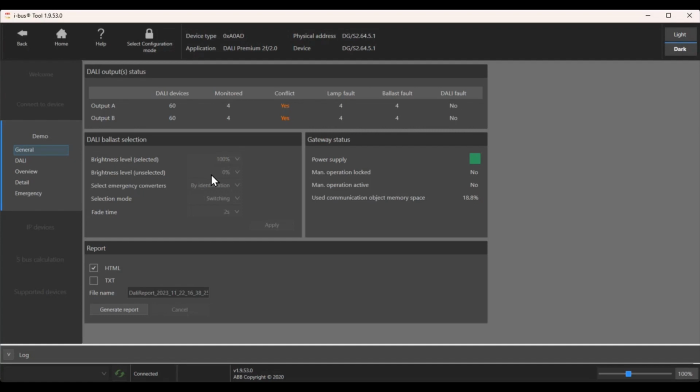As long as they're connected to power inside the site and they've got Dali fittings on them, without any programming, without any integration, without any KNX bus, these can be turned on, and the installers, being the electricians, can press a broadcast button and turn the whole network on and the whole network off. This is really, really handy for you guys that have done any kind of Dali, and you understand that some of the most labor-intensive part of the Dali network is figuring out faults when you're first there. If you can eliminate that by putting in your terms and conditions within your quotes or within your projects that the installers and electricians must test the Dali network before you get there, then this is going to save you lots and lots of time and hassles.